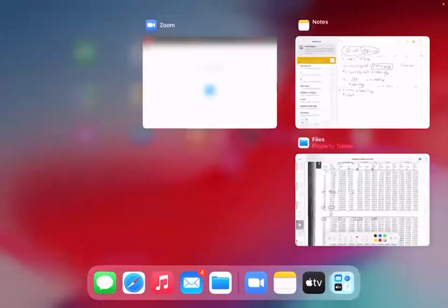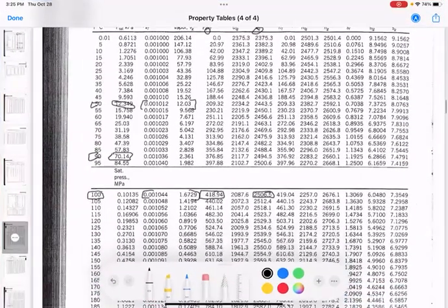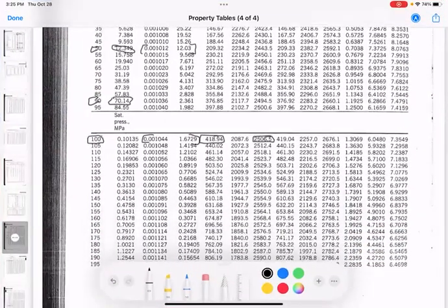If we go here, let's see, maybe it's a mixture. If not, it'll be superheated. 150 is the temperature, and we check whether the V that we have is between the right values. Is it between these two values? Yes, it is. We have about 0.2. So we're still a mixture, but now we're at a different state.